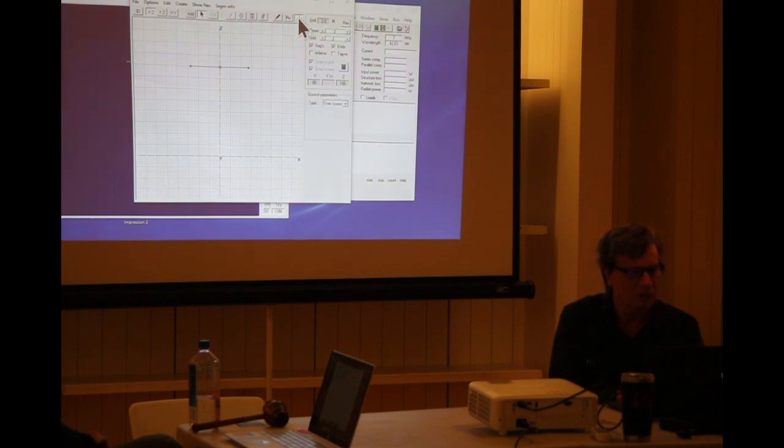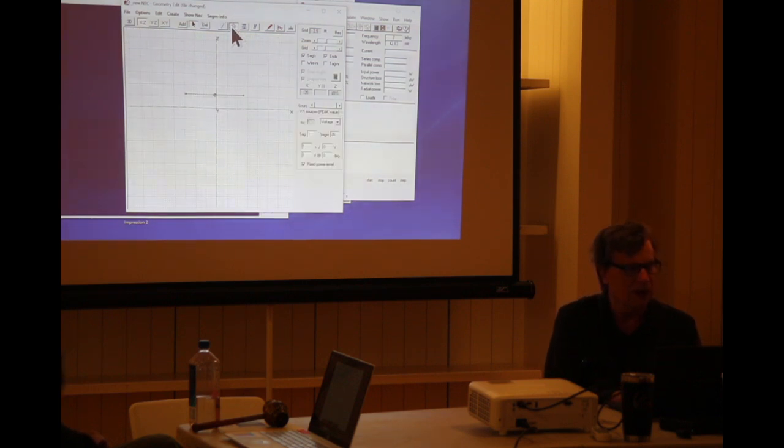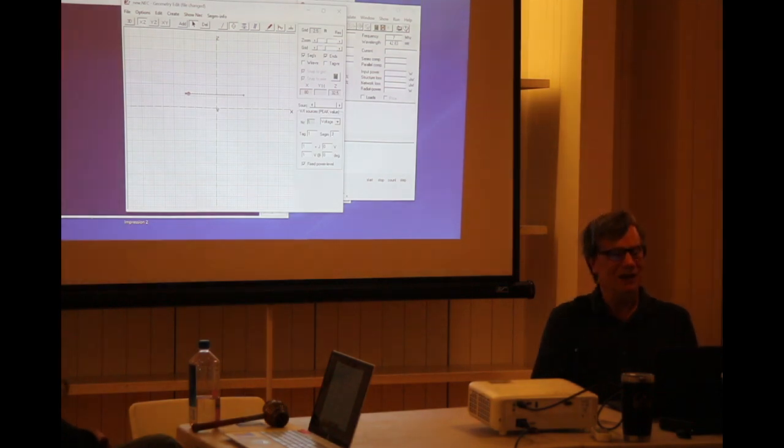I'm going to do this in free space, and I'm going to move this down a little bit, just to keep things easier to keep on the screen here. So I'll scoot this guy down. Okay, so this will make this a little more convenient for me. And what we'll do is we'll take our feed point, and currently our source is on segment 36, about the middle of the thing. Well, let's put this on segment 3 instead, okay? So our source is way near the end of the wire.